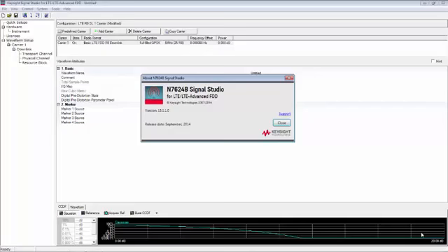In other words, an EVM measurement is a measure of how far the actual measured values are from the ideal locations. This measurement needs to be made quickly and accurately, and when testing transmitter components such as an amplifier, be accompanied by a clean test signal with enough EVM performance to provide an adequate test margin for the device under test.